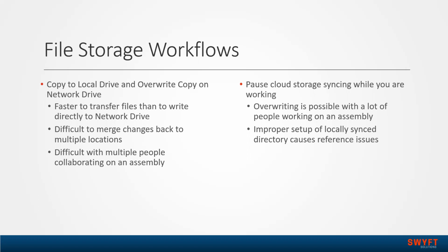And then pausing cloud storage is another one that I already mentioned. You just have to be aware that cloud storage generally syncs to a local user profile. So we can get all sorts of broken references because it saves to that local user's file path, and then another person opens it and can't find them. So there's ways to overcome that, but none of them are just easy out-of-the-box solutions.